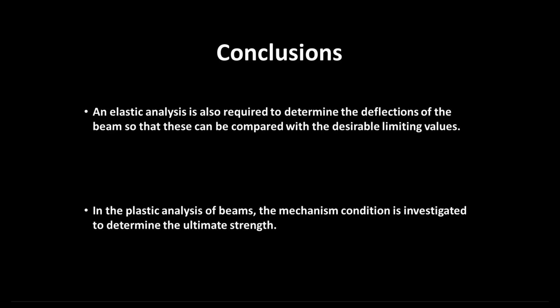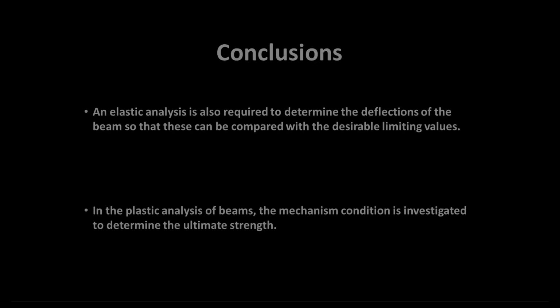From the conclusions, what have we learned? An elastic analysis is also required to determine the deflections of the beam, so that these can be compared with the desirable limiting values. In the plastic analysis of beams, the mechanism condition is investigated to determine the ultimate strength.